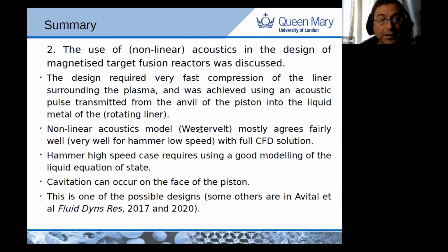We looked at nonlinear acoustics for the design of target fusion reactors. Mostly there was good agreement between the nonlinear acoustic model and the full CFD. When you have high hammer, high speed, you really need good modeling of the liquid equation of state. There was a problem there of cavitation that is not accounted for by nonlinear acoustic models, and other designs, I have to say, are possible. Some of them are in these references. So the designs are moving forward. This is a really fast-moving field all the time.